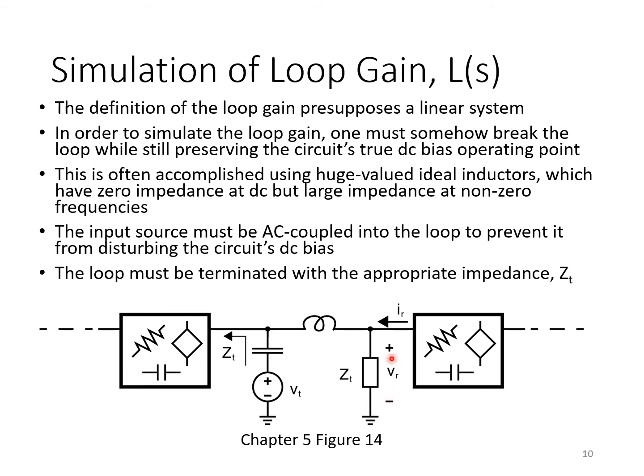And finally, don't forget, we do need to introduce the terminating impedance, ZT, over here. If ZT is not purely capacitive, you may wish to introduce a large AC coupling capacitor here as well, so that it doesn't disturb the DC operating point analysis either.